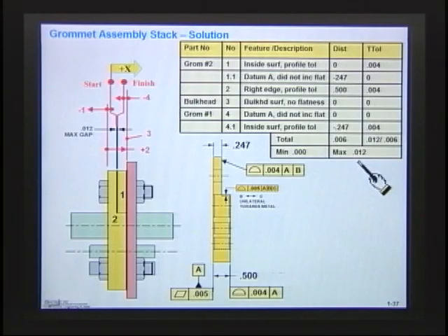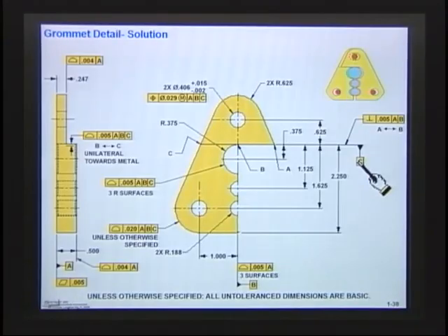All right. What's next here is this is our solution, and this is our part. What I'd like to do is to just talk about the solution. You have the solution in front of you, and maybe a little bit how you would inspect the part. Not that we have to go in and inspect the parts, but just generally, how would they go about this? What would they do? Now, you remember what our datums were. I don't have to do this over again, but A, and then this here was datum B, and this one was datum C. So let's take a look at our models here.